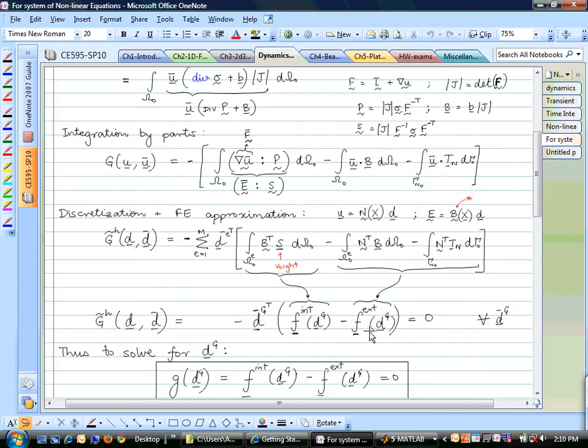When can that happen? There are problems like hydrostatic problems for submarines, where the pressure is always normal to the surface of the submarine. If the submarine bends or flexes, the pressure changes according to the current configuration of the submarine. So the applied pressure, the external force, is also, in general, a function of your displacement.